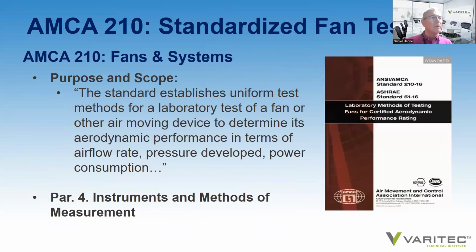So AMCA 210, what is AMCA 210? The purpose of the standard is to establish uniform test methods for a laboratory test of a fan or other air-moving device to determine its aerodynamic performance in terms of airflow rate, pressure drop, and power consumption. They also define the tools and instruments to be used in generating that performance data.